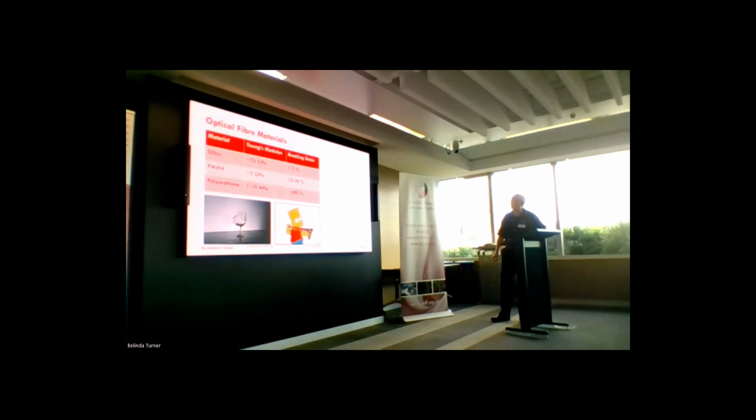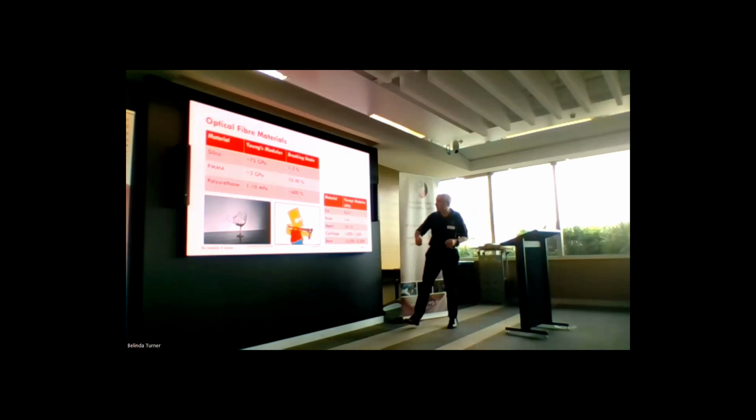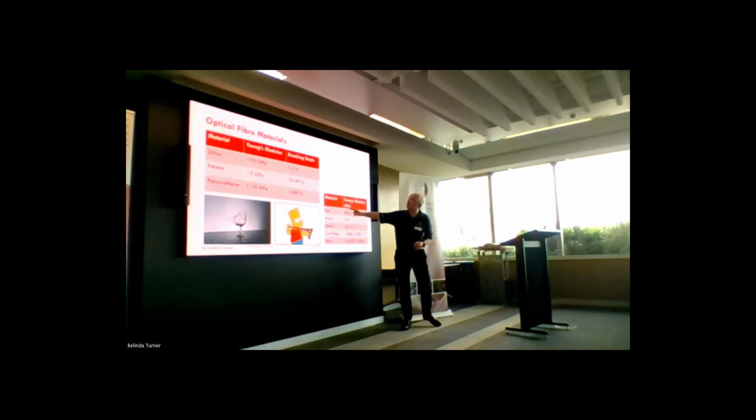The other thing, when you're looking at sensors, especially sensors for wearables and to do with the body, is how it compares to the material that it's sensing. So this gives a range of Young's modulus, this time in kilopascals, not megapascals, for things from fat through to bone. And polyurethane sits somewhere in this region.